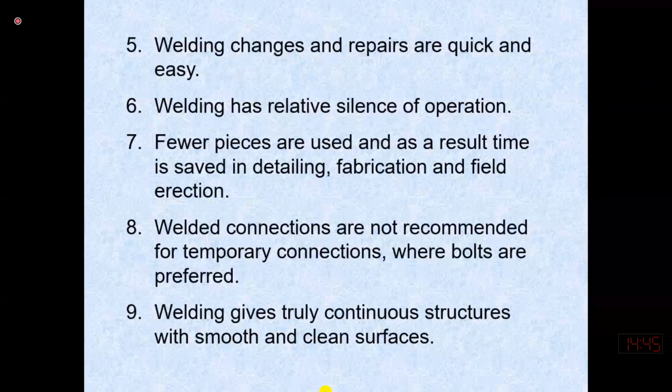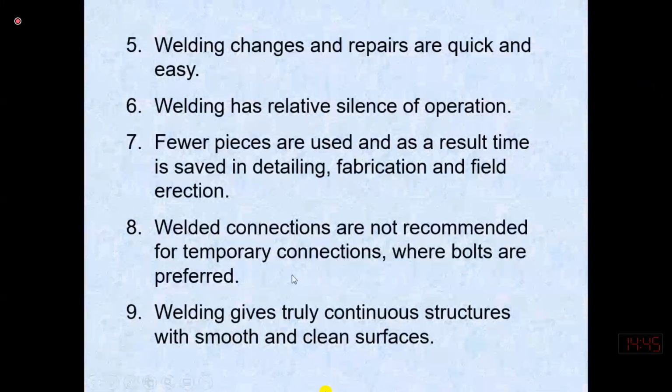So welded connections are not recommended for temporary connections, where bolts are preferred. Temporary means, for example, scaffolding or temporary site offices, which we may need to disassemble and re-erect again. Welding gives a truly continuous structure with smooth and clean surfaces. So that may be more aesthetic.